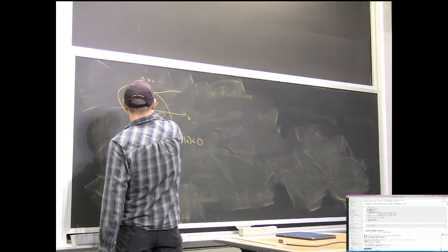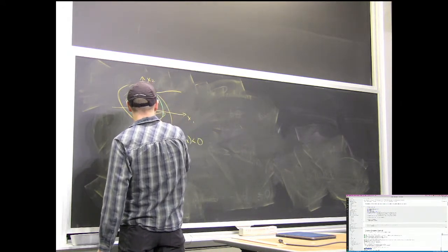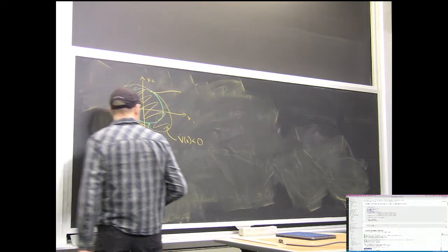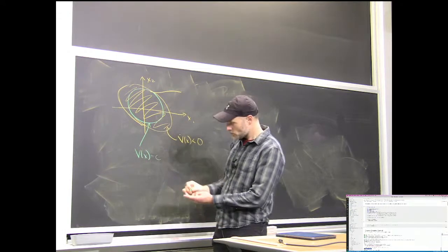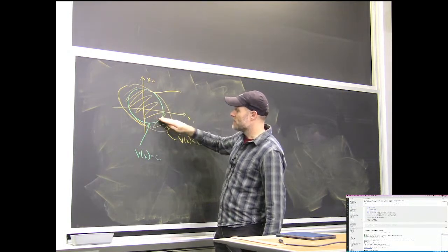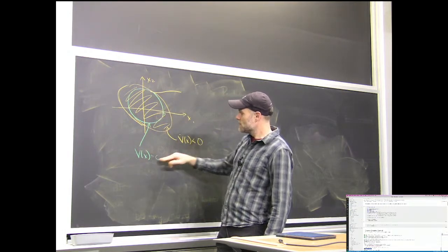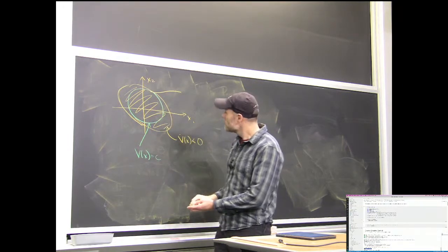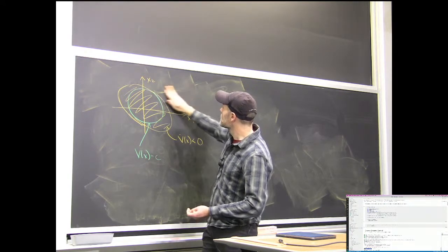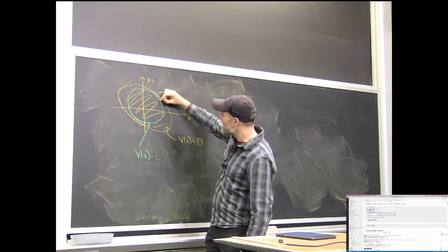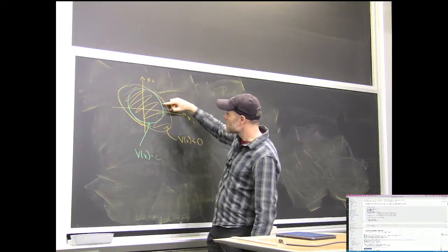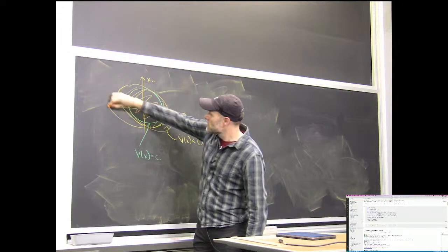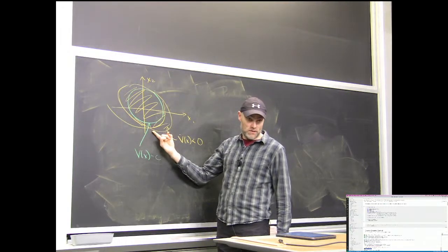Okay. There's another set of things I could potentially know. If I have level sets of V, for instance, if this is a V of x equals C level set, this is an invariant set. Any sub-level set of my Lyapunov function is an invariant set. If I start outside the invariant set, there's no guarantee. Just because V dot is going downhill, it could leave the set potentially.